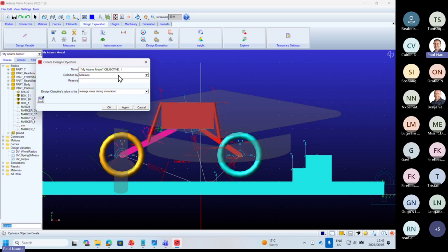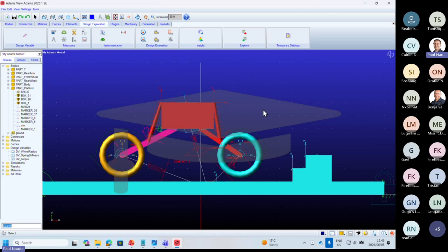What you could do is to say, okay, I'm going to measure the torque, and I'm going to modify the torque, and I'm going to modify the radius of the wheel, and I'm going to measure the body's velocity in this direction. And then I'm going to set a goal that it has to pass this point at a certain speed by changing the torque and wheel radius values. So that would be one example where it becomes valuable.